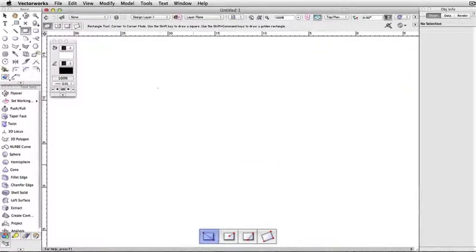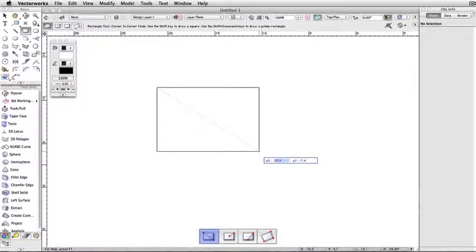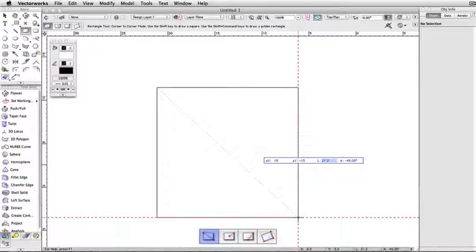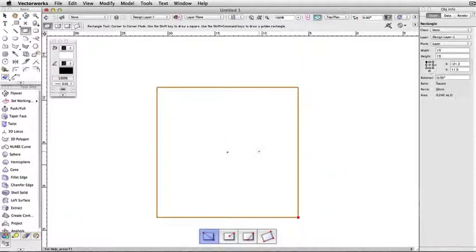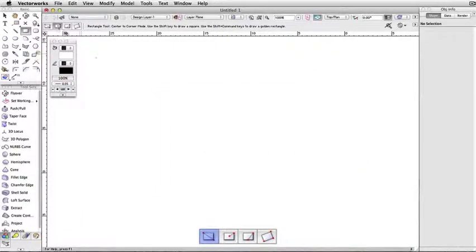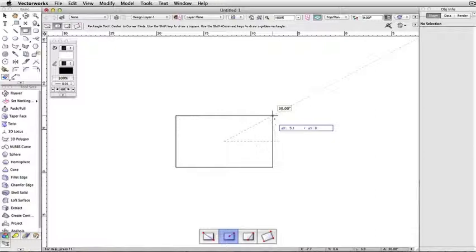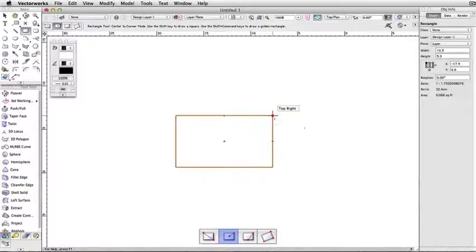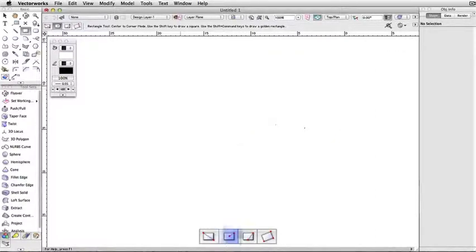During any of the drawing modes, you can press the Tab key to enter the width and Tab again to set the length manually. These are expressed in the floating data bar as delta X and delta Y. The second mode, center to corner mode, causes your first click to set the center point of the rectangle to be drawn, then your second click to specify any one of the corners.